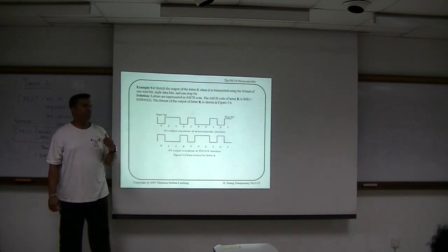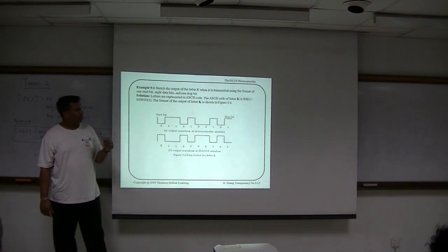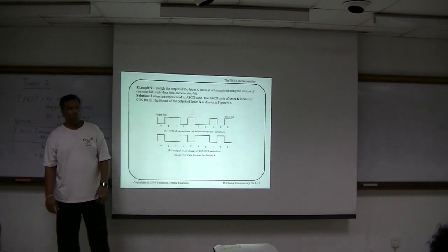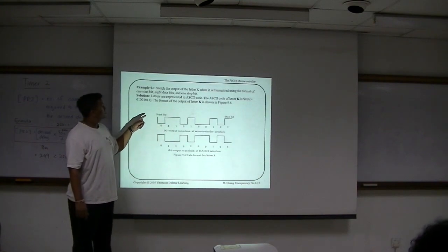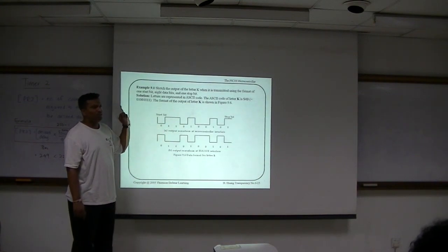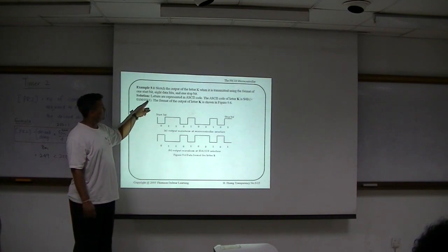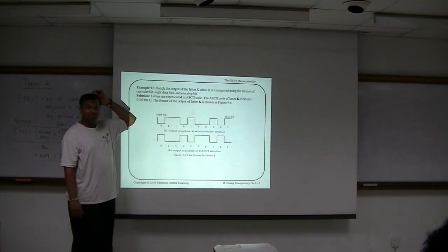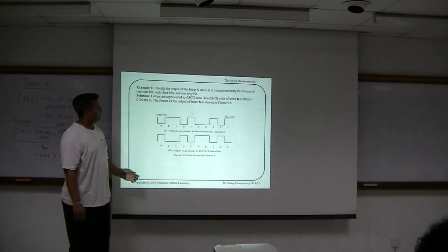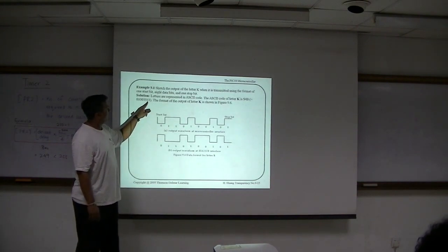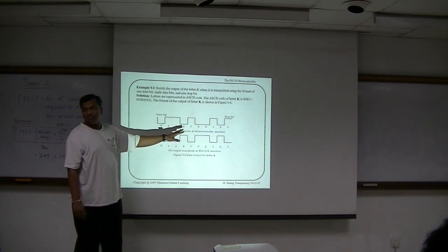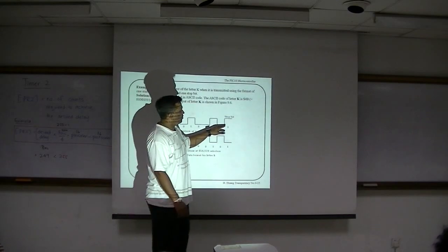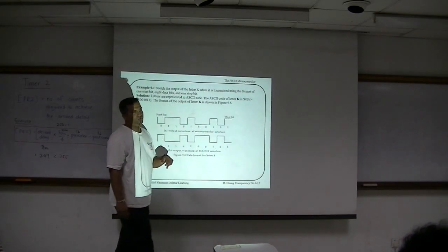So you need to send it using the USART format, with 1 start bit and 1 stop bit. Always remember, the start bit is always 0. Take note that whenever you send, it starts from the least significant bit first. So that's why it will be 1, 1, 1, 0, 1, 0, 0, 1, 0. Do you see it's reversed? Then after the last one, the stop bit is always logic 1.